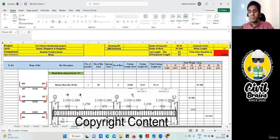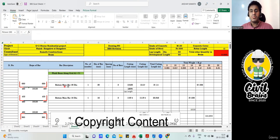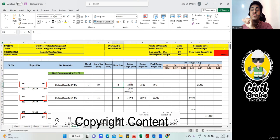Great. So I'll delete this part now. Now it's simple. Bottom main diameter is 20 diameter, and the number of bars was 2. How will you find the cutting length? Very simple. Add this 680 plus 460 plus 10,150 plus 460 plus 680. If you add everything, we'll get the total cutting length of the bar.